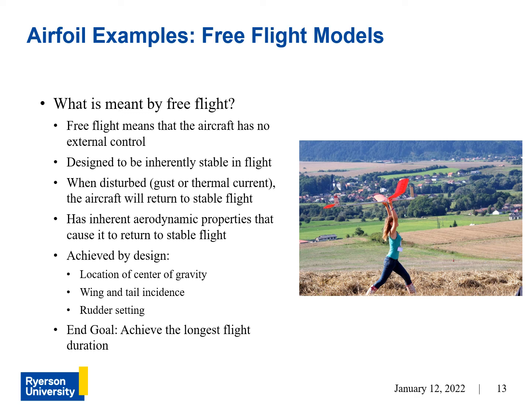And this is achieved by design. So by the location of your center of gravity, your wing and tail incidence angle, so that just means angle of attack with respect to your fuselage, and rudder settings, so the angle of your rudder if you have one. And the end goal is to achieve the longest flight duration.